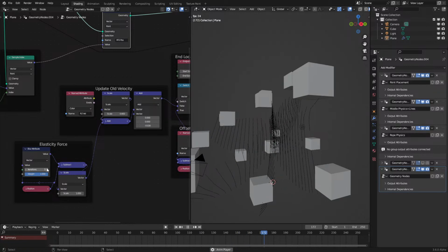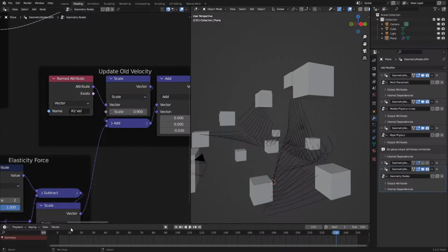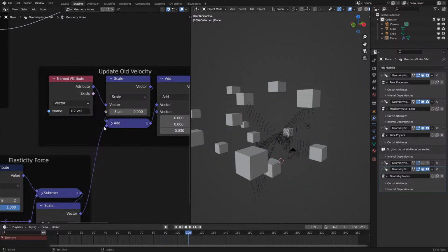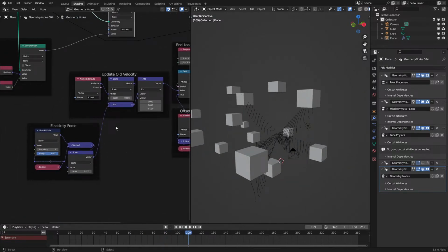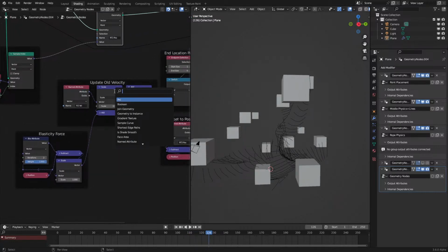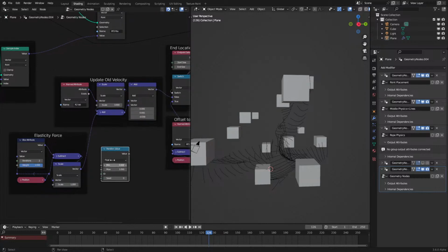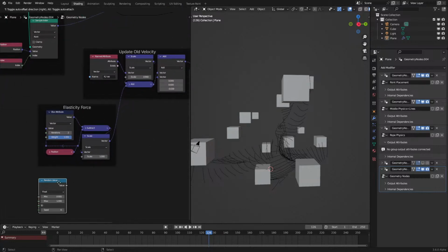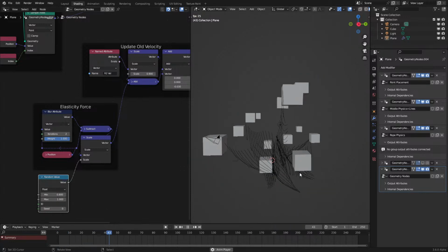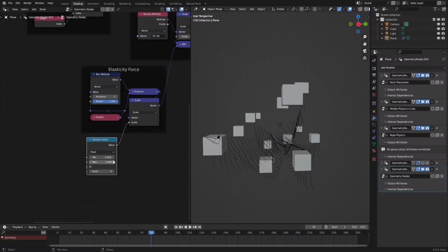Oh, looks like we're going to have to... Oh, that's why. Wait, why did that happen? Okay, there we go. Now we have the secondary ropes doing that, but I want to change the random length of them. So for that, I'll go and randomize the elasticity scale to be like 0.8 to 1. Oh, and this needs to be on the spline domain, so evaluate on domain.